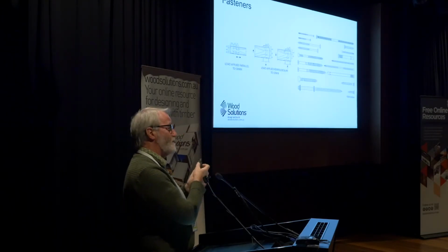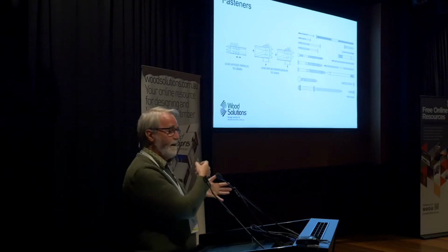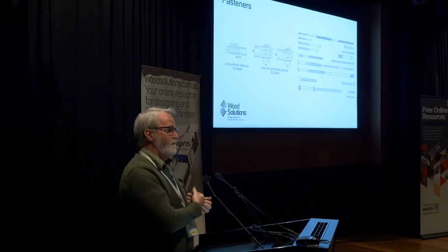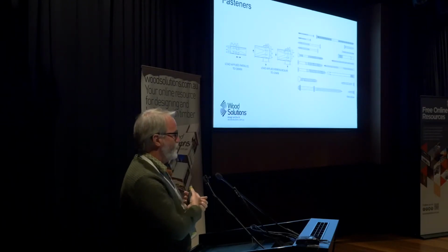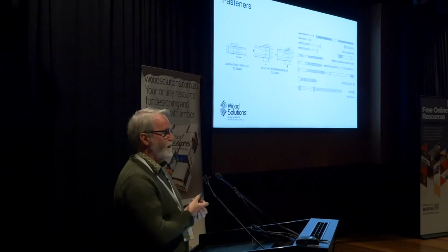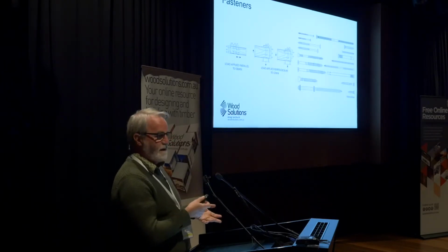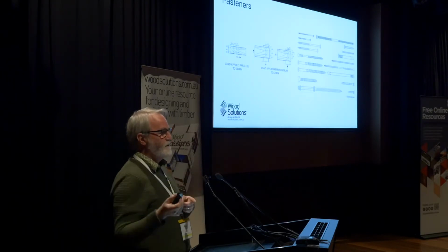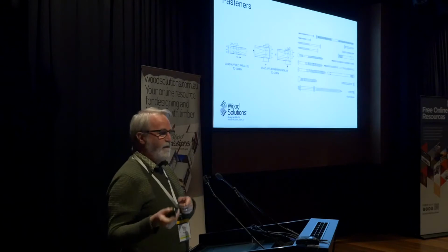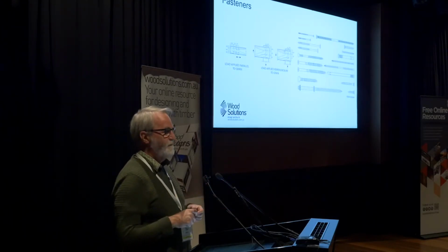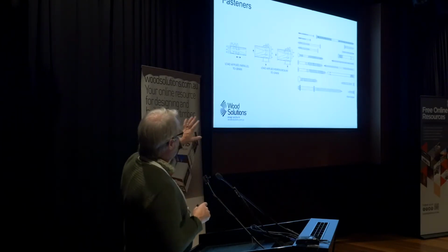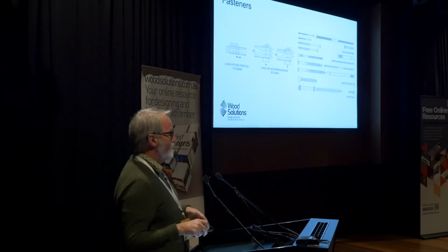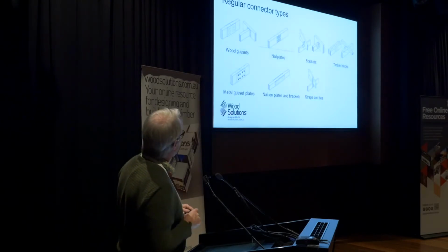Now, part of the reason we've put quite a lot of detail into this connection bit is that my engineering colleagues tell me with great conviction that with most timber structures, actually God is in the details. God is in these connections, in that the connector can actually be the thing that determines the size of the element rather than simple things like bending or strength. So we have obviously then considered exactly how these connectors may go together.